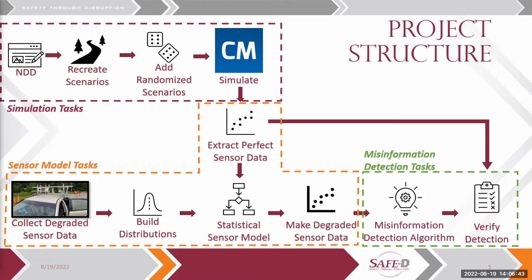So for example, we might take a near crash event, change one of the parameters like lane position, and suddenly it becomes a more traditional baseline type event, and completely changes the output of what the sensor response is. And from there, we're able to simulate those recreated events, and we do that within CarMaker. They've got a fairly robust list of sensors that we can use to capture that environment data within the simulation relative to the sensor specifications that we apply.